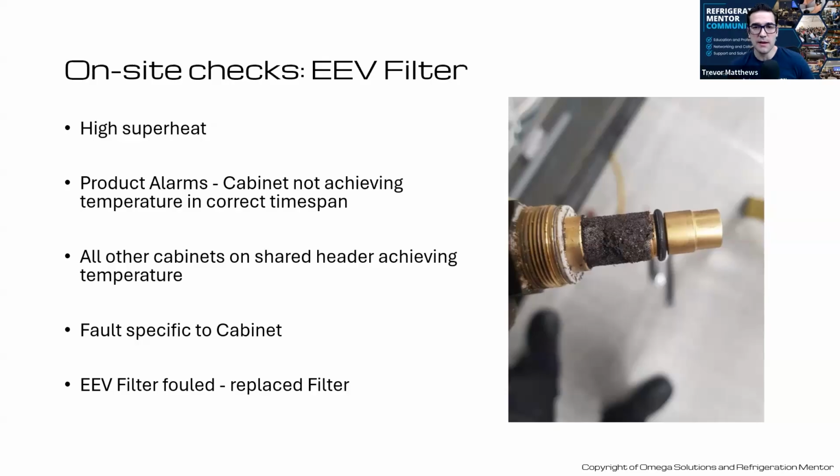You may not know that, like it may not be what you're used to in a TX valve, where it's very noticeable. This one here is not noticeable. This is inside. You actually have to take the valve apart to look at it, pump down the circuit safely, pump all the refrigerant out, and then reclaim whatever's left in the lines. This is another thing that I just learned from a technician in one of my CO2 courses.